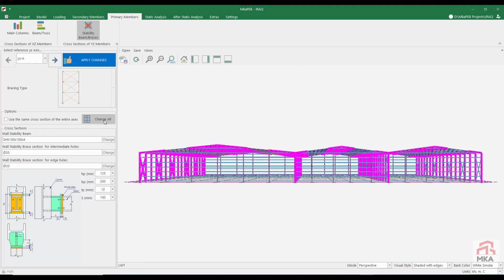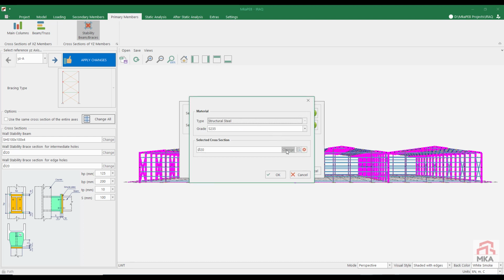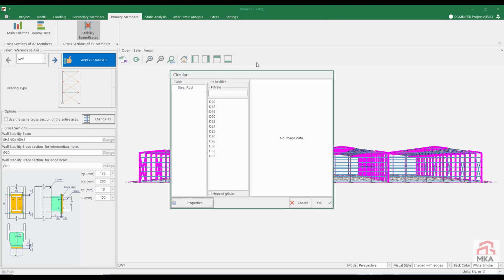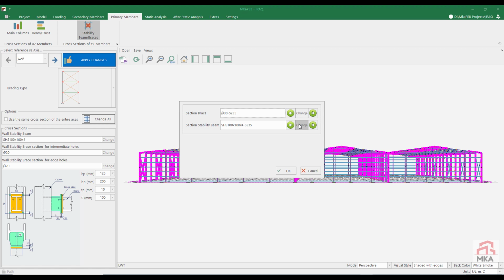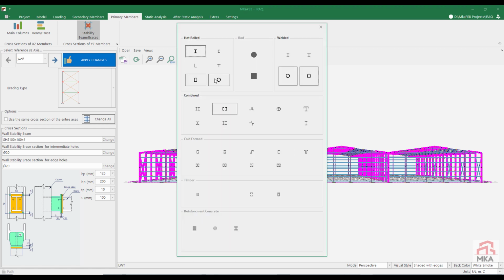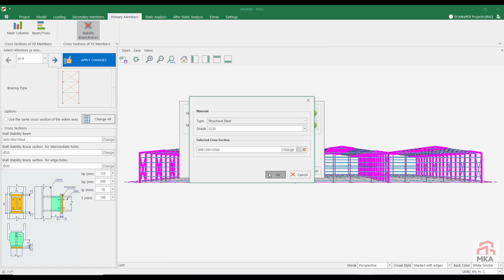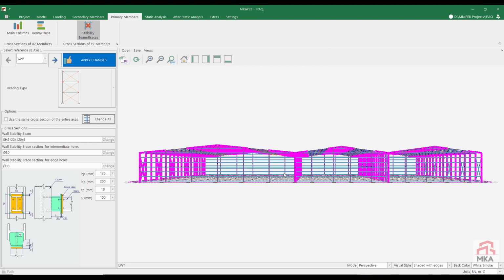We will use 30s rods, not 24s. We're also going to make the stability beams a little larger. I'm changing the braces here to D30. I also changed the stability beam to SHS126. Those on the middle axis will be slightly larger.